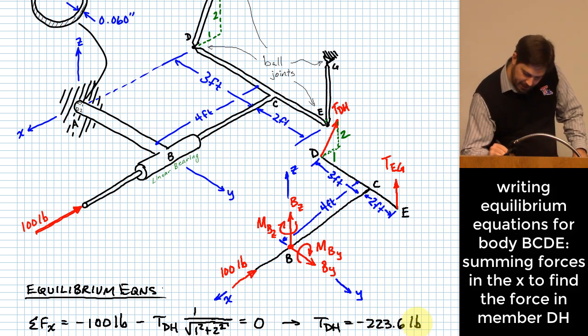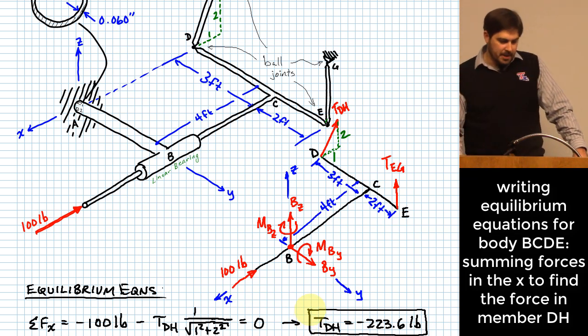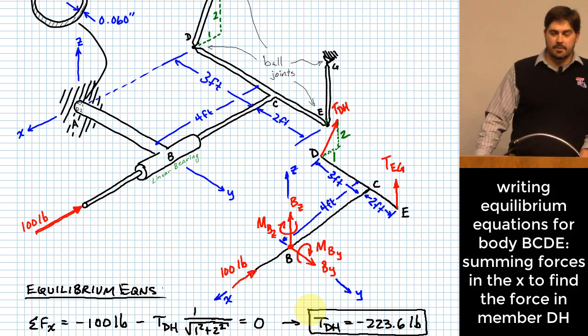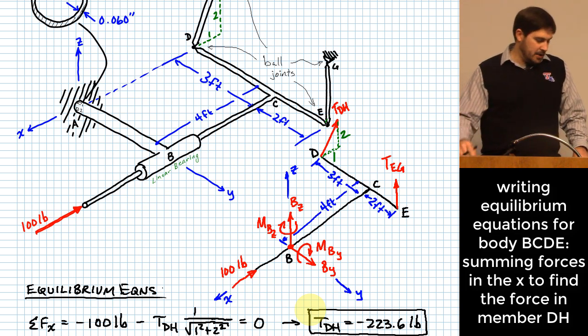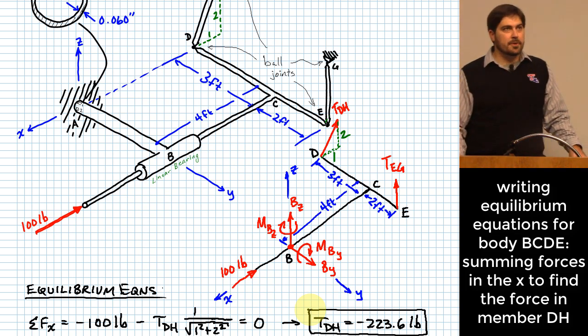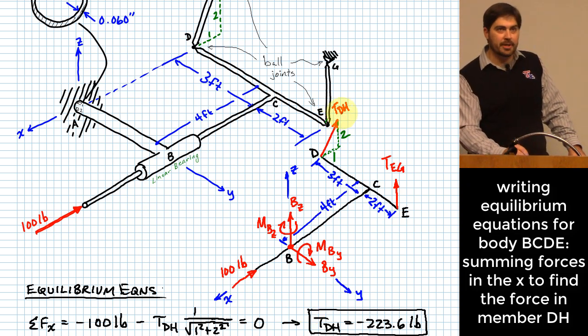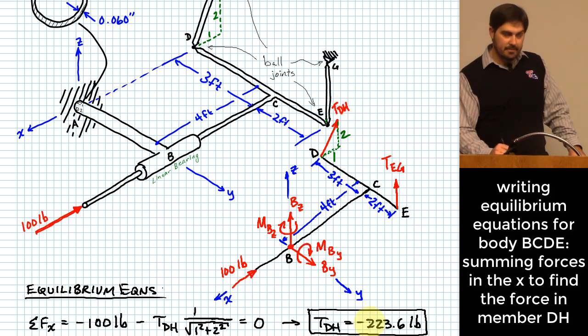What does that negative mean? Okay. It means that the direction I showed the force is actually opposite of what it really does. And especially with respect to two force members, if you define them like I did here, and I even named it accordingly where I used T to indicate tension, the negative means what?